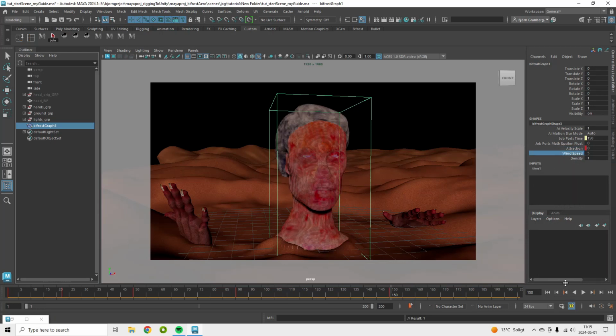Now the wind speed. I'm going to start at frame 60 there, and there the wind speed will start at 0, and then at frame 90 I'm going to raise that to 10. So that's it, and the density on frame 100, key selected, so density 1, and then it's going to disappear on frame 160, 0 out.